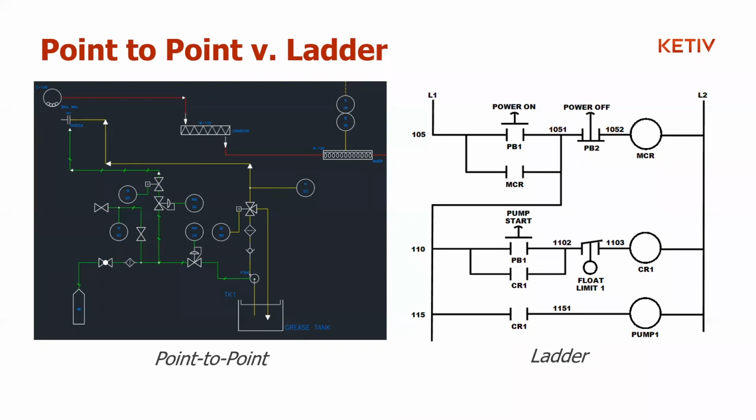Right. So if you were like a technician on the floor doing assembly, for example, you wouldn't necessarily need the ladder diagram. It might be more beneficial to have the explicit connections listed out point to point as opposed to in an abstract ladder configuration. Okay. And it goes without saying, but point to point is technically a bit more flexible. So you could kind of have a bit more control over how your drawing looks and how it's presented, and looks a bit nicer and gives you a few more options ultimately at the end of the day.